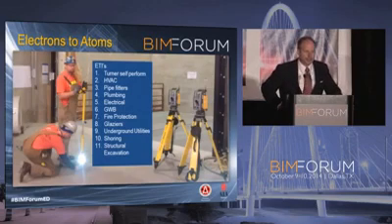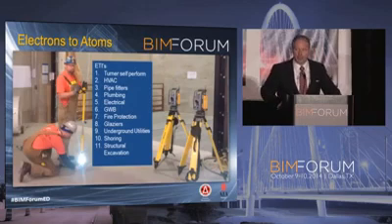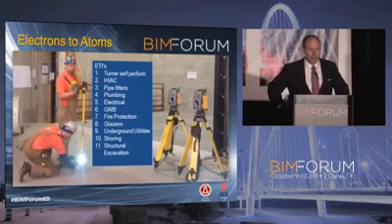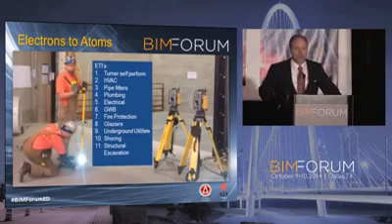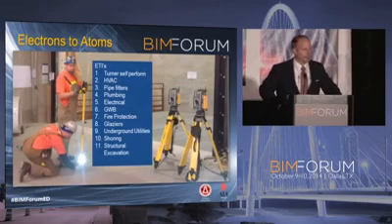Everything in the old days went back to grid. Today, everything goes to the coordinates. The coordinates match. This is one of the keys. On the latest job that we've got, 11 different trades using total stations. For the first 7, I won't even contract with you if you don't have a total station taking your BIM model to the field. Okay? Everything goes back to the coordinates.